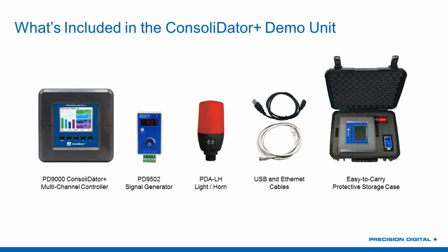Working my way up here, Greg has asked about the 24-volt power supply I mentioned. All right, well, that's not purely Modbus related, but I'm certainly happy to cover that. So his question is, I hear you write that every 4 to 20 milliamp input has a power supply. That is correct, so let me just make sure that it's clear what I mean by that. So every 4 to 20 milliamp input on the consolidator has its own isolated 4 to 20 milliamp power supply.